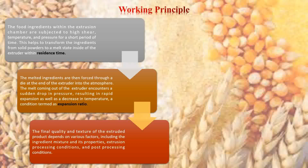And the next step is the melted ingredients are then forced through a die at the end of the extruder into the atmosphere. The melt coming out of the extruder encounters a sudden drop in pressure, resulting in rapid expansion as well as a decrease in temperature. A condition termed the expansion ratio. Let me describe the terminology of expansion ratio.